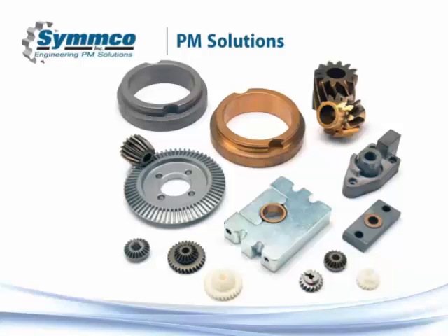Okay. And is it possible to achieve a bearing race, i.e., say 5210 HRC 60 properties when pressed and sintered with pressed and sintered powder metal? Yeah, we do have a few parts where hardness, a wear surface, is critical. And again, we can create those HRC 60 particle hardnesses.